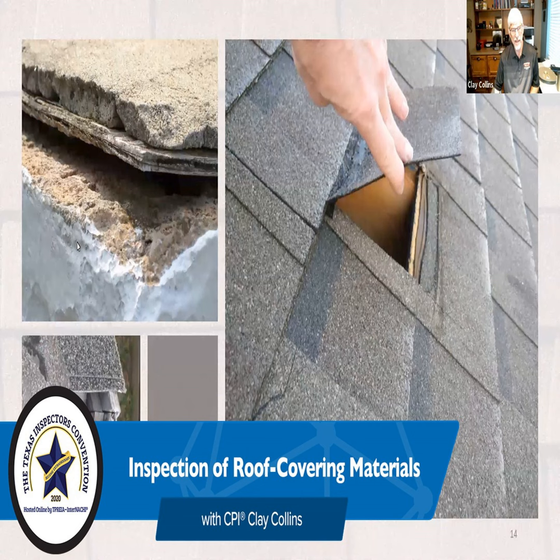There is flashing designed to go on the roof, installed like any other roof boot, and it's up off the ground, up off the roof deck, so that you can mount your antenna to this. It's raised and it looks like a box off the ground. So all the fasteners are under here, and it is installed as flashing should be, in shingle fashion, and the antenna does not penetrate and compromise your roof. But you see this an awful lot of the time.